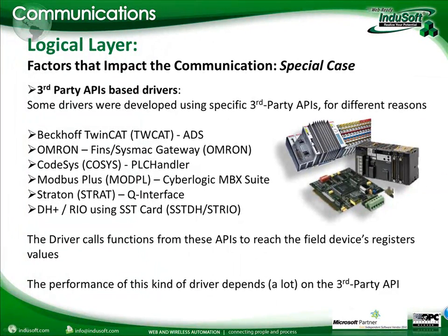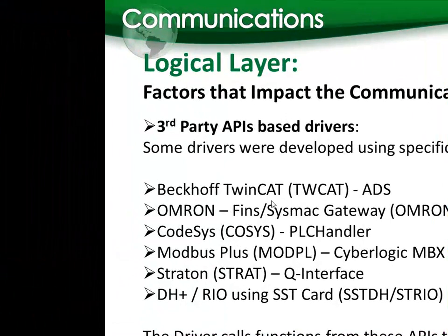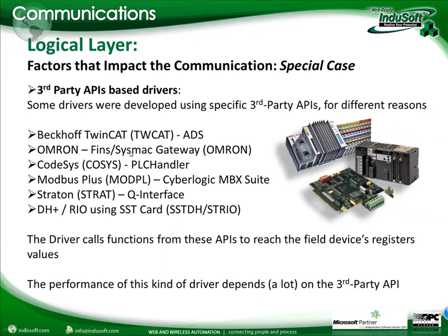Okay. In a similar way, we also have the Omron driver that goes through the FINS or SysMac gateway. We talk to the gateway, and then the gateway goes to the network. It doesn't matter if it's their EtherNet/IP, their DeviceNet, their Controller Link network. For us, we are just talking to the FINS or to the SysMac gateway. Okay, and there are other similar examples like Modbus Plus, where we talk to the CyberLogic APIs, and the CyberLogic goes to the PLC.